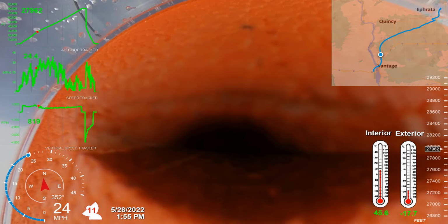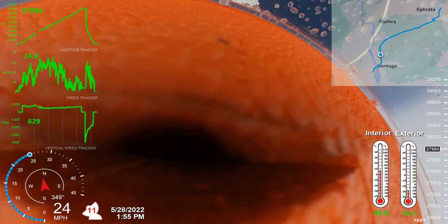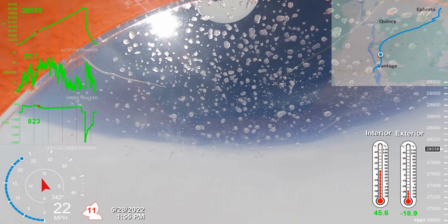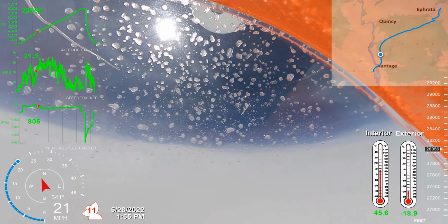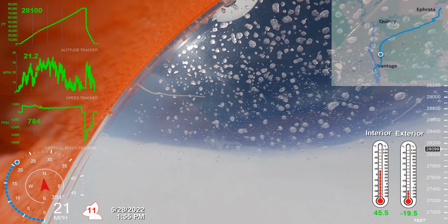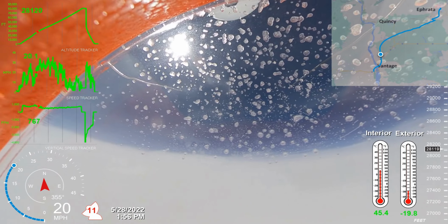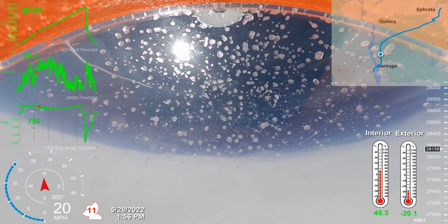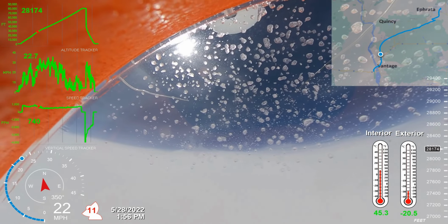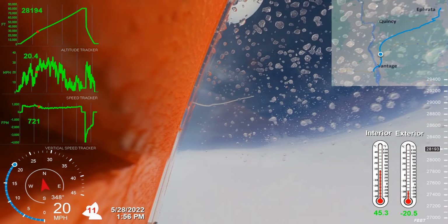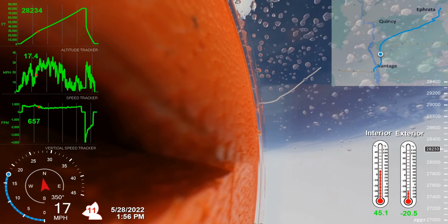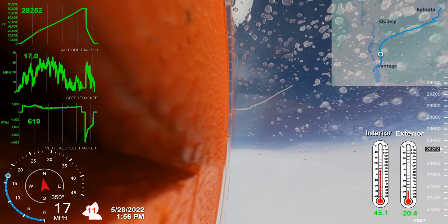The main problem was that we didn't actually capture the entire flight. As I mentioned, we only got around 37 minutes of footage. Now, unlike the still camera, this wasn't because the battery failed. Instead, this was because we forgot to erase the SD card before launch, and as such, the SD card was actually already 78% full. Therefore, it only left us 22% of the card available for recording the actual mission, which translates into around 37 minutes of footage. So again, this was due to our oversight when we were developing the checklist.